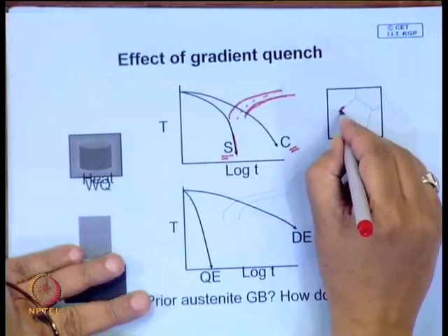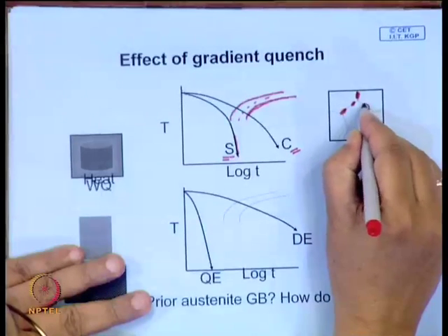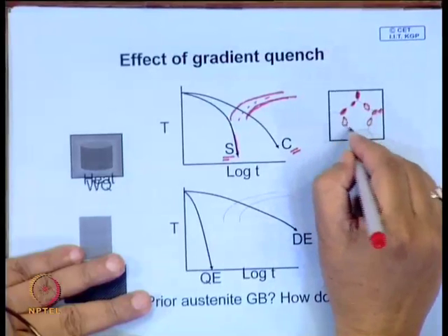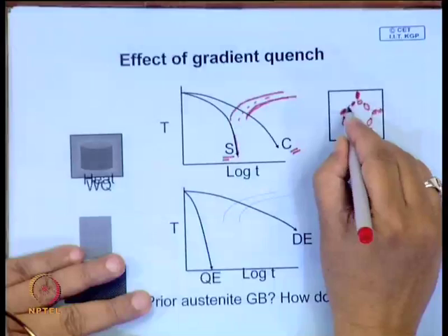The surface will be totally martensitic, and in between you can think about certain cases where you will have pearlite forming. These are fine nodules of pearlite, and to start with they will all form along the grain boundary, along these triple points. So, they get nicely marked.